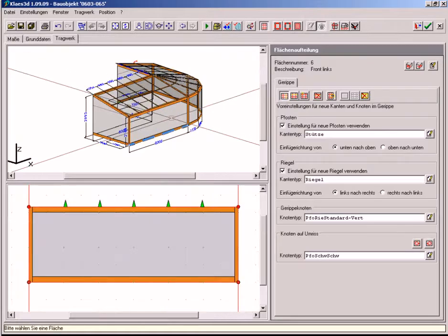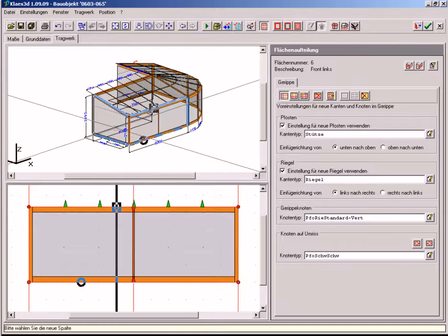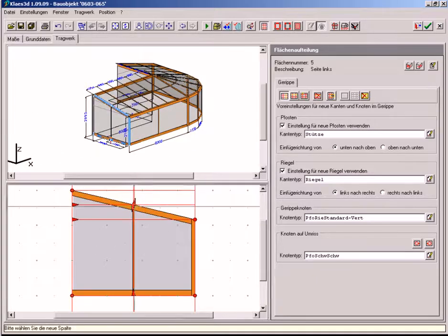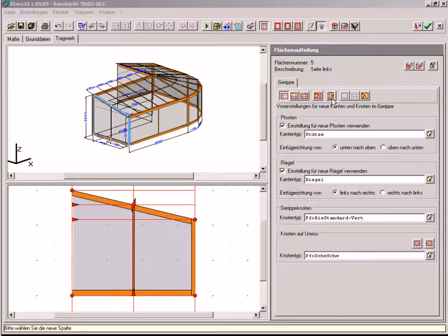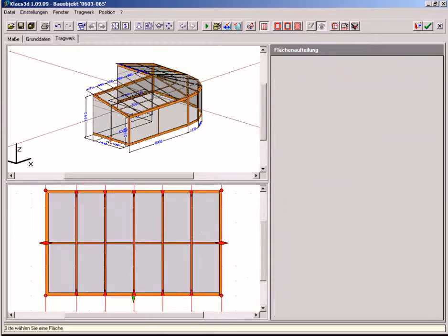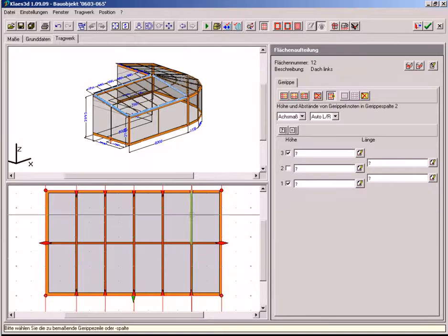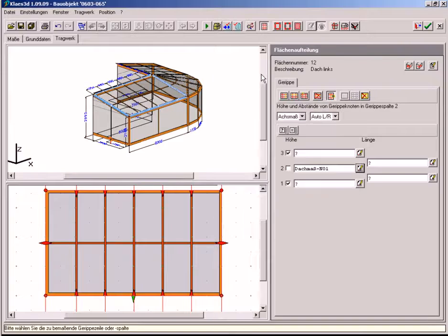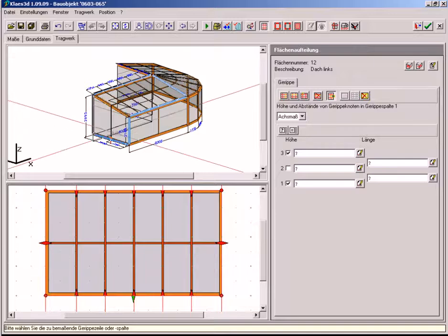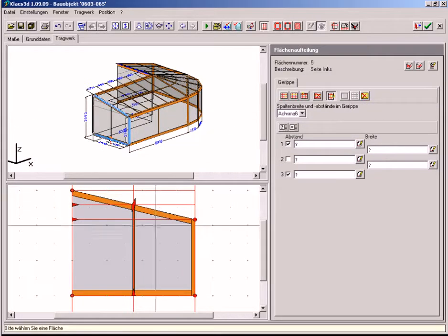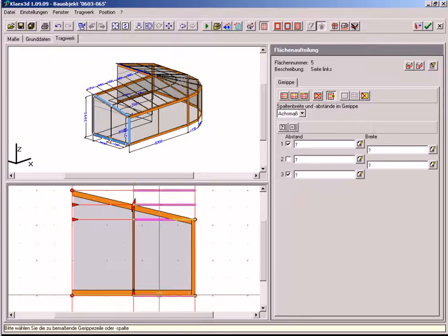The left face of this construction is supported by a construction wall or backing. The left edge automatically has a prepared joint between the backing and the glass panel on the roof. Now, a cutout takes place. The roof pitch dependent measurements from the basic data are used for the cutout depth at roof surface. The new cutout dimension can now be used to reposition the existing bridge rafters.